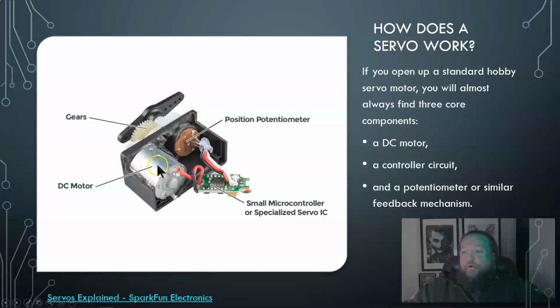So that's your motor right here that's actually doing the moving, but then it's connected to gears up here on the top that handle stuff for torque, because that DC motor with that spinning can't handle like torque or friction on it, but the gears then help translate that. So these are different size gears, different size teeth that are then connected to this external part that will actually move, so that you can control the movement and you can also deal with a little bit of the torque issues, but you have those limitations.